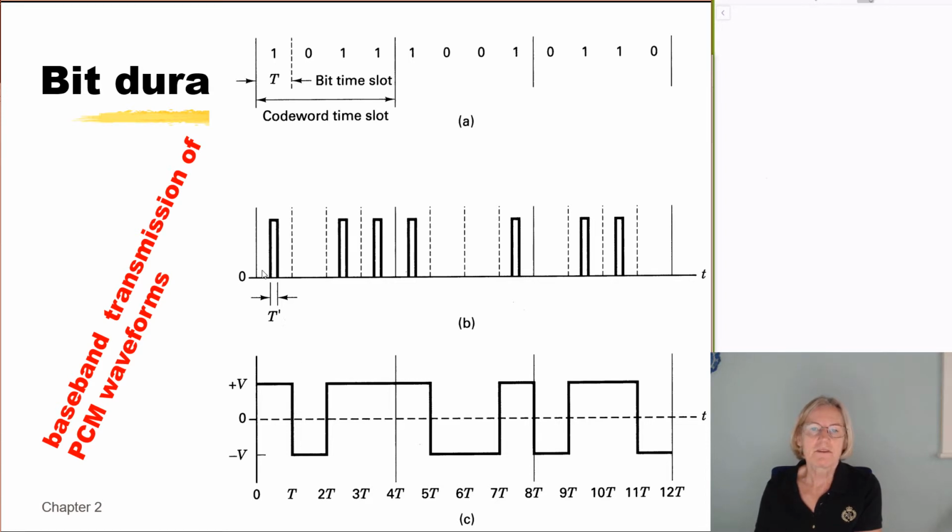In here, we look for a logical 0 voltage and some other higher voltage level. And this is a very short pulse of some level. Now, here is another example of how I might choose to send that PCM waveform. Suppose I did two levels, so there would be a logical 0, but it would be a negative voltage, so this is a differential type of voltage. That would be another solution. It's still binary. I could assign this a logic 1, this a logic 0. And in this case, I'm occupying the whole time of the bit.